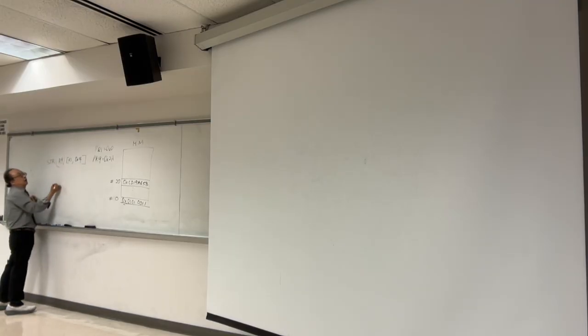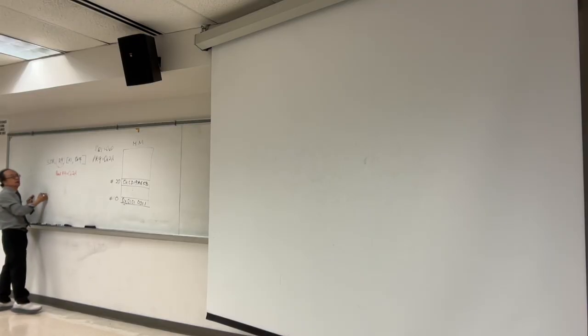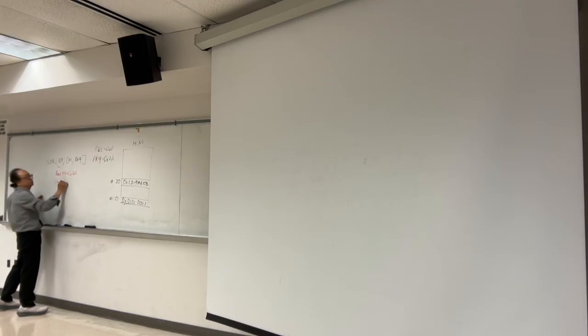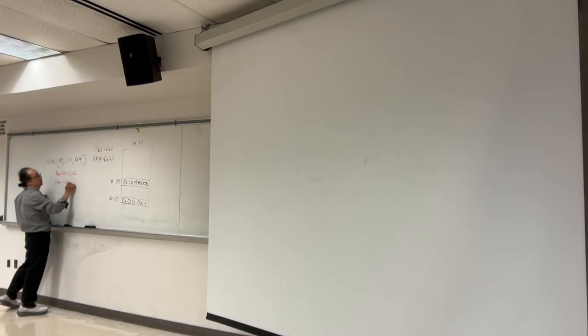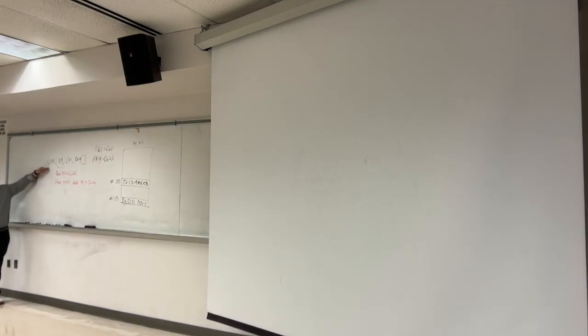Store, this is our source, so we need to read R9, which is 0x2A. That's step 1. And then we need to store into main memory at the address R1 plus 0x14. Those are the two steps for STR.